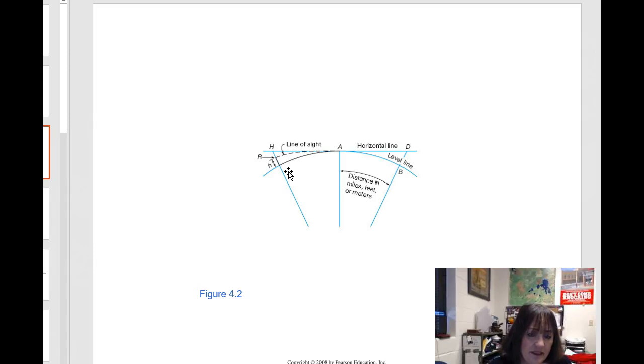It does not have to be at an angle of 180 degrees, because if you think about it, the surface of the Earth is a three-dimensional surface. So if you go 180 feet due north, and you just turn maybe 75 degrees so that you're going not quite due east, even though your two lines look like this, as long as they're the same length, the curvature and refraction is going to balance itself out.